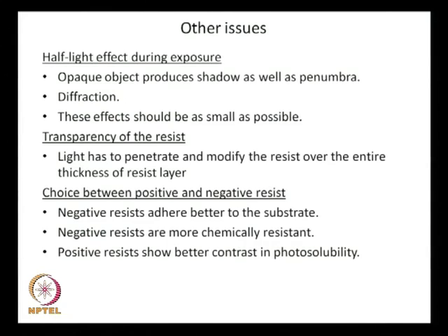Then there is this choice between positive and negative resist. You may ask, I have a choice, now which one to take? The practical suggestion would be: negative resists adhere better to the substrate. Negative resists are more chemically resistant. On the other hand, positive resists show better contrast in photosolubility. So, these are the pros and cons of these two resists, and when people develop protocols, they develop them based on these understandings.